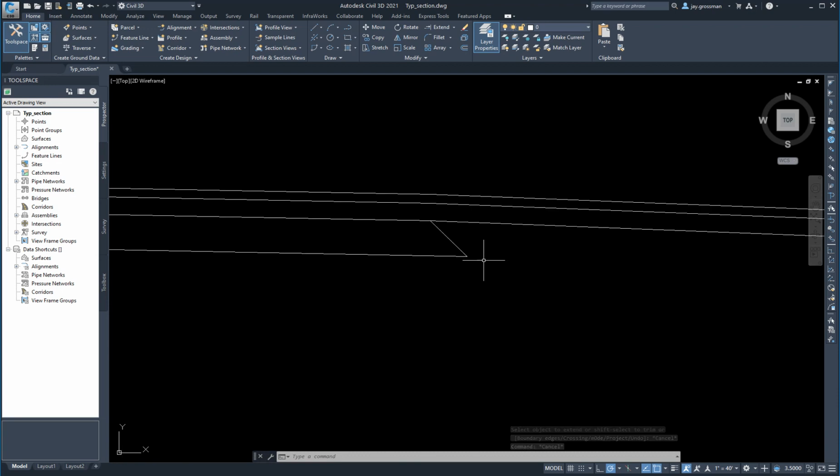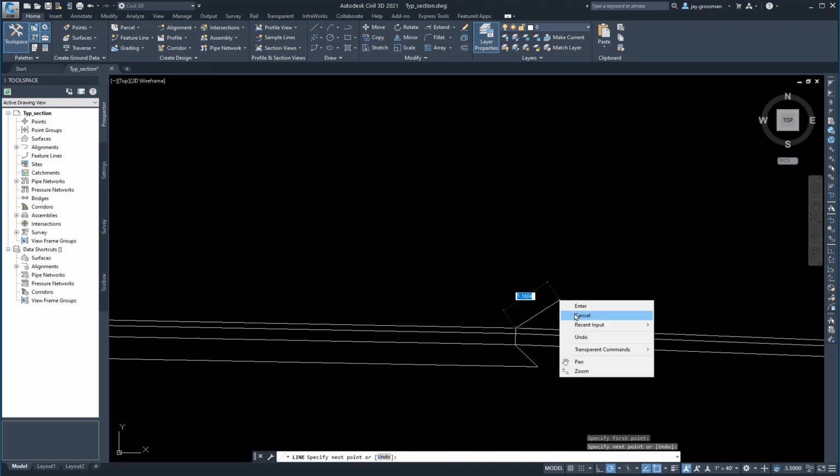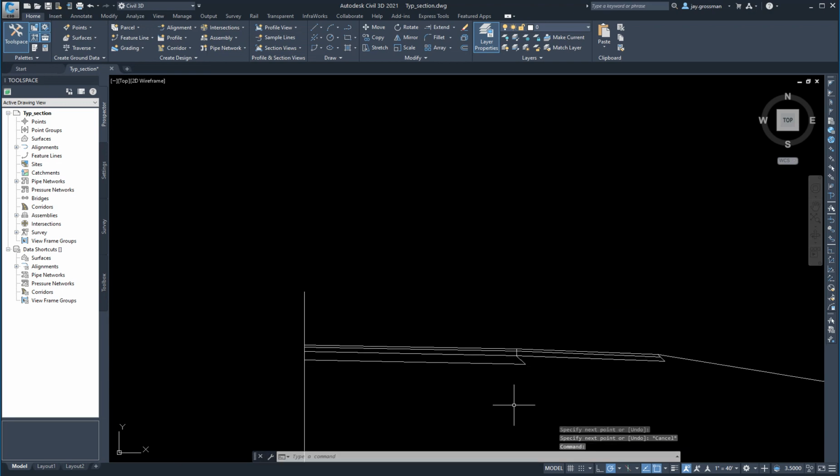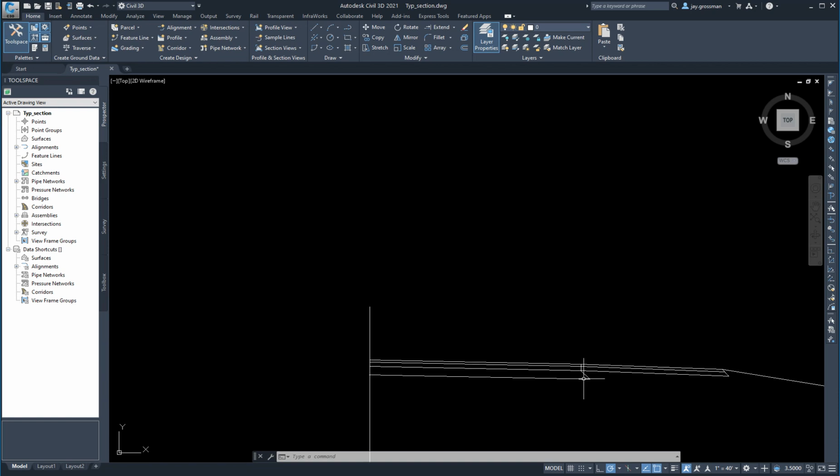All right, for that. And quite often we change the type of material between the shoulder and the main line pavement. So that would show that difference there if you want to draw a line in there. All right, this could be a higher quality asphalt. This is a lower quality asphalt on this side of the line. If they're exactly the same, then you wouldn't show a line. If they aren't exactly the same, we could show it that way.